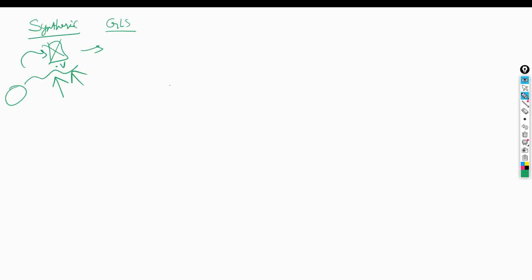Earlier, GLS was post PNR. Once the PNR is done, timing details are extracted based on the standard delay format, the SDF file. You will annotate it, meaning your gates will mimic the delays. Let's say you have a flop. There is a clock to Q delay. Whenever the clock is triggered, from D to Q, there is a delay. There are billions of flops, so a lot of delay is introduced. So you annotate that delay and run the netlist. You do post PNR GLS. Earlier, this was the case. Now these companies are also using it.